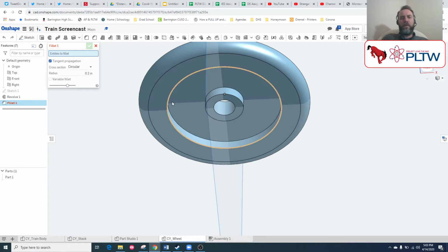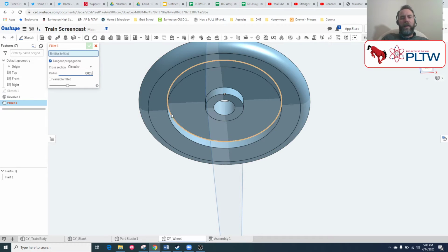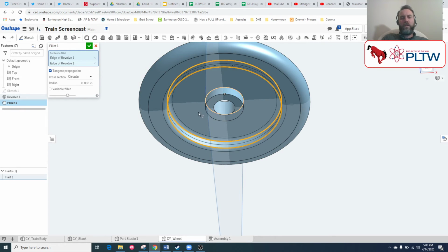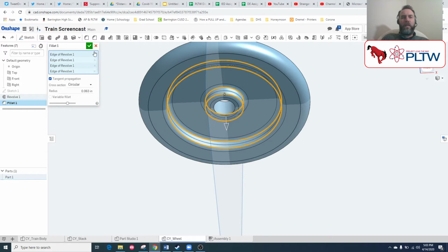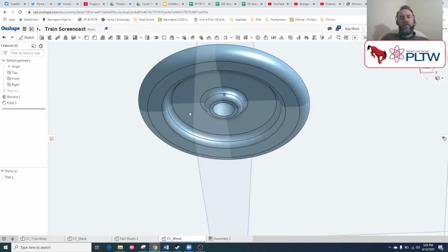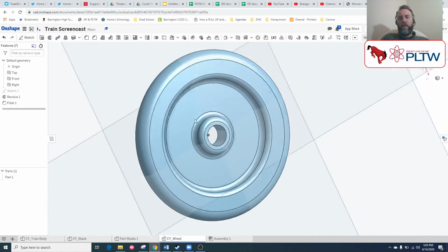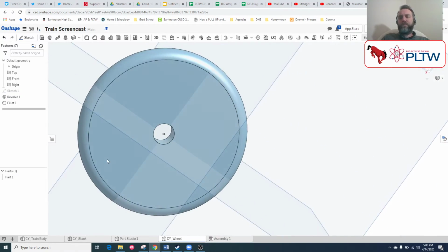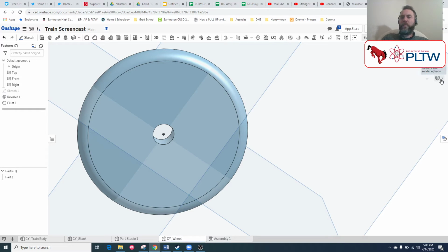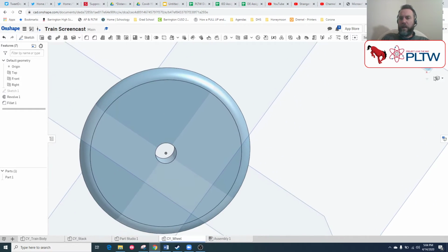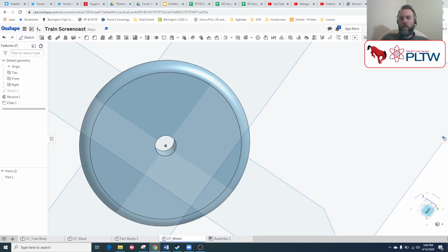Now when I do my 3D fillet, if I type in 0.0625 and I select those 4 edges, I think it should have no problem. There you go. Alright. That took more work than it should have. Hey, nothing's going to be perfect here. We're streaming live, including I did not move the view cube down to the corner.